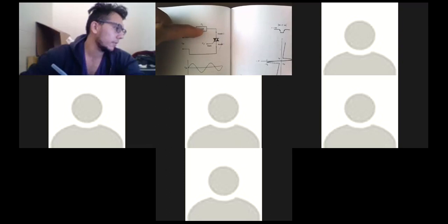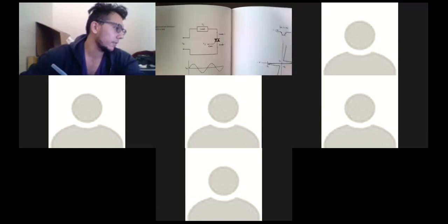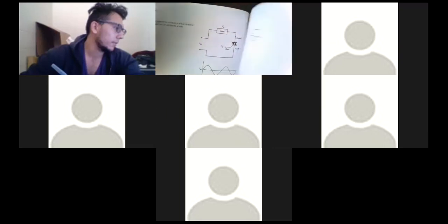Obviously, some light bulbs do not work with the dimmer because these switches frequently turn the power on and off, and some circuits or appliances are not designed to have the power turned on and off like 60 times every second. It's actually turned on and off 60 times every second. So this is a triac.